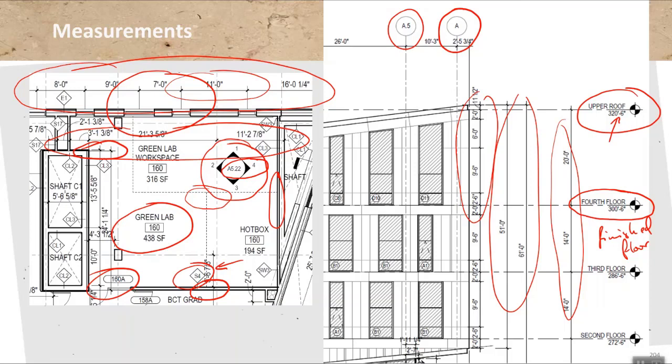We've got the dimensions called out. Last thing you see here are also the window tags, and you can see, of course, because all of these windows have different dimensions, most of them actually do, those with different dimensions are numbered differently. But as you can see here, these two windows have the same dimensions, so they get the same number. Those two windows get the same number, and so on and so forth. So that is window tags.